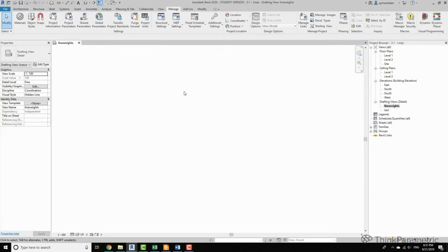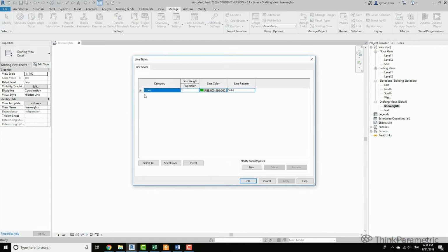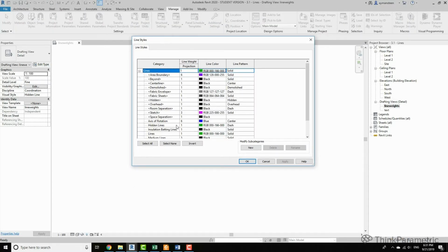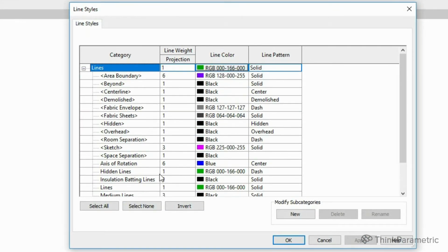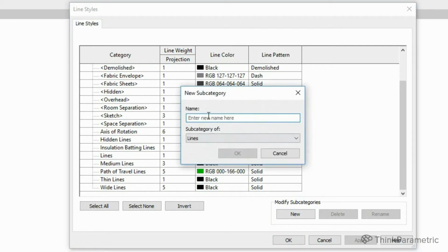So to start tweaking the line weight setting, we'll create the line styles corresponding to the line slots from 1 to 9. Let's go to Manage, Line Styles, and expand on the plus sign, and start creating new line styles.